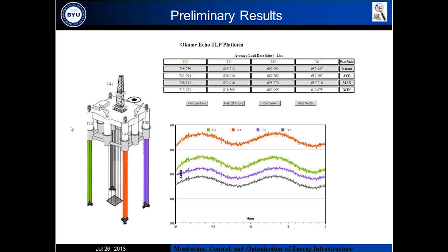For example, if the value that is being reported by their load cells is 700 kips, I have an additive part in my model, and I give it to the software, and the software, by looking at the exact measured value, finds out what the additive part will be. For this, I have hundreds of lines of code, and when you go into it, it's a little tricky. But now it is done, and we are able to calibrate it very easily.